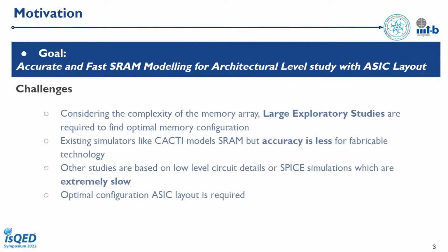Hence, the current challenges are: considering the complexity of the memory array, large exploratory studies are required to find the optimal memory configuration. Existing simulators like CACTI model SRAM, but the accuracy is less for fabricable technology. Other studies are based on low-level circuit details or SPICE simulations, which are extremely slow. Optimal memory configuration and ASIC layout is required.